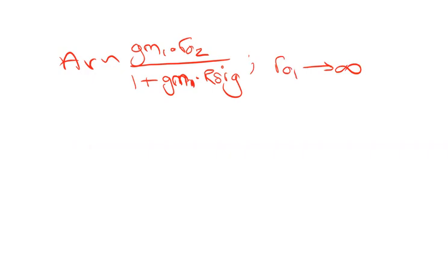We made that assumption just to simplify the small signal analysis, with the assumption that R01 does not change the overall gain equation by much. You could include R01, because in the frequency analysis, we did include R01. So you can also go back and include R01 in this gain derivation. It just becomes more complicated. There are more equations to solve to get the result. Okay, so I hope that helps you understand a little bit about how to replace the resistor with an active load and gives you some understanding of what happens in a common gate amplifier when you do this.